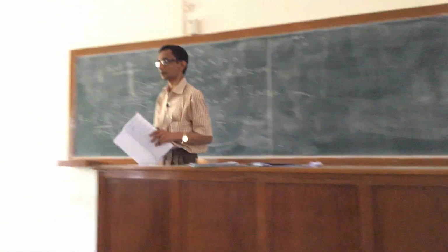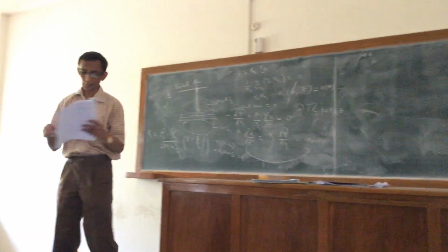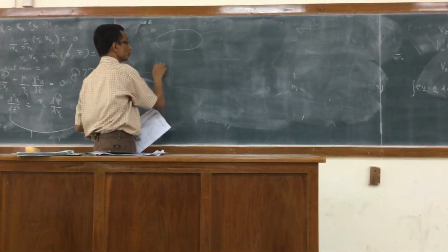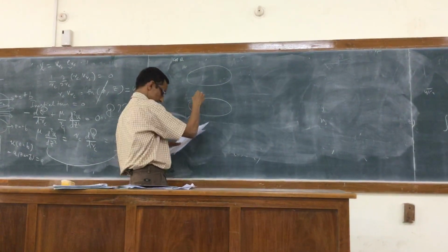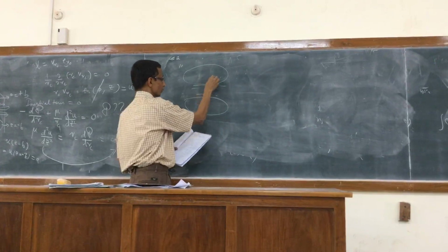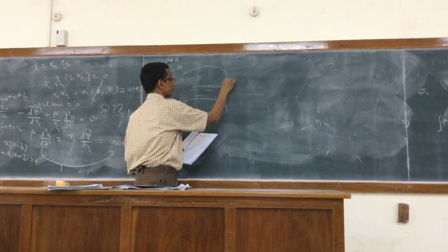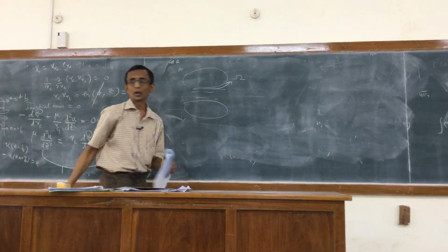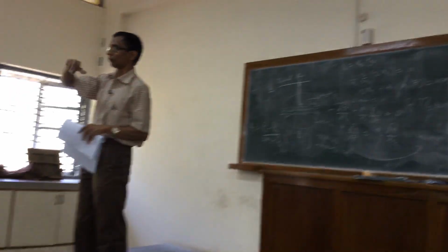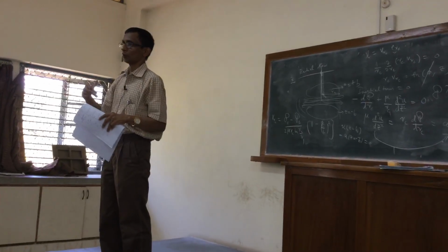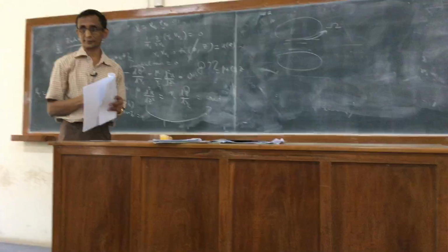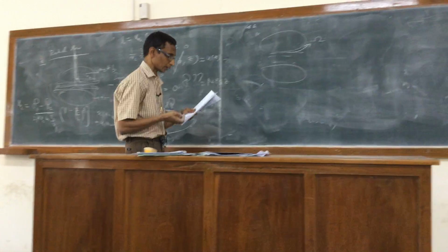How to calculate the viscosity of a fluid in a parallel disc viscometer, where again I have two plates and there is a fluid between the two plates, right? The top plate is rotated with omega. So it's sort of a d-phi motion, but now the fluid is between two plates rather than between two cylinders. So this is what we call the parallel disc viscometer.